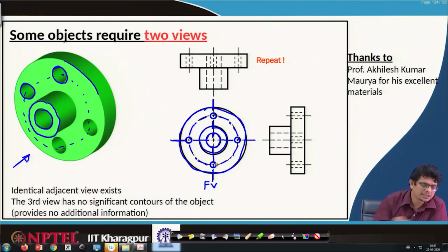The immediate thing is to use the top view. On the box method, when we are going to look at that, this entire object is projected. So, the projection lines are bounded by these tangent lines.